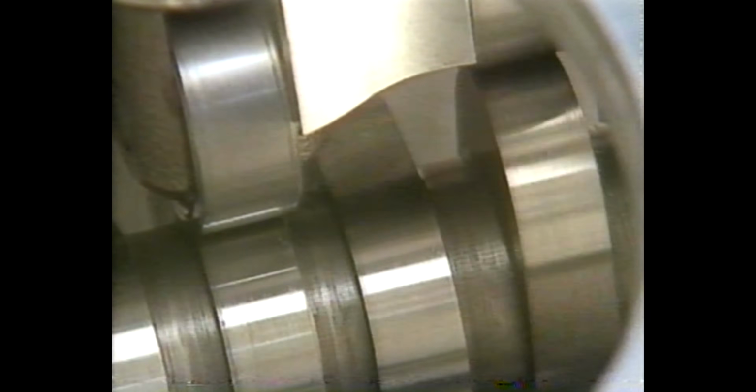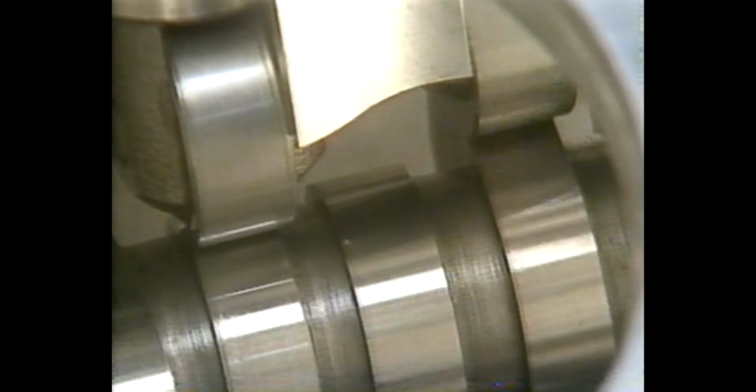For example, when we first start our engine, the oil is cold and thick, making our oil pressure slightly higher. This in turn overpressurizes our hydraulic lifters, forces the lifter's hydraulic pistons up past their normal operating positions, and alters our valve timing. The altered valve timing will cause our cold engine to idle roughly until it reaches its normal operating temperature, at which point our oil pressure will be at its design value. The hydraulic pistons will return to their normal operating positions, and the original valve timing will be restored.